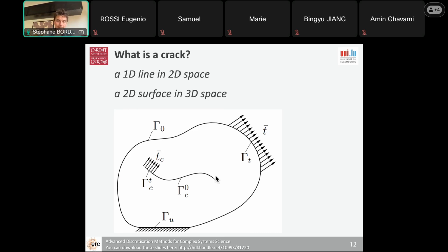That means, again, if you are a little ant that's moving around, as the little ant crosses the crack, which is here noted as gamma 0c, as the ant crosses that thing, well, you have to handle a discontinuity. And that discontinuity is the problem that your finite element solution needs to handle.